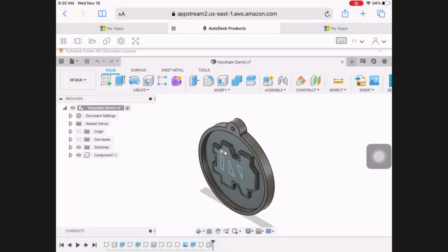Okay, so hopefully you have your Google Drive set up, and this is going to walk you through how to get your tool library. So all of the tools that are in our mill, I have already set up for you, but you need to load the library of tools, which has all the speeds and feeds and all the settings into your Autodesk Fusion library.